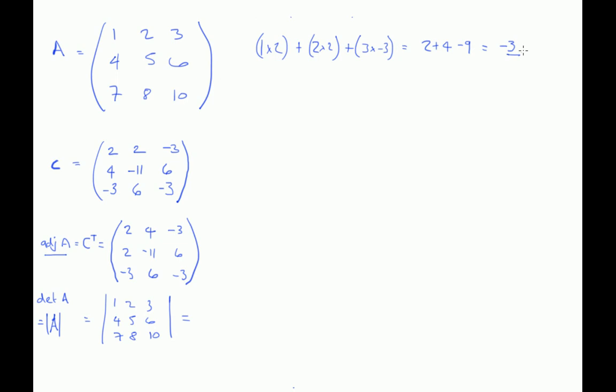And that's why we had to change this 9 to a 10, because if you divide by a determinant that's 0, then you get infinite. It's a non-soluble or non-invertible matrix. Sometimes you get something that is close to singular, so that you get a poorly conditioned matrix, and the computer can't invert the matrix, or if it does invert the matrix, errors creep in. So that's something that we as engineers have to watch out for when we're modelling structures.